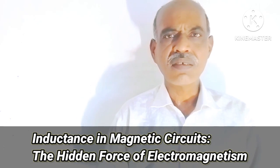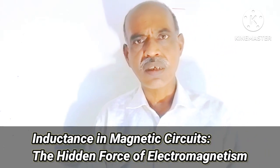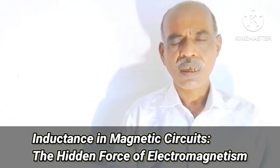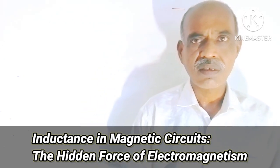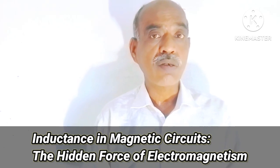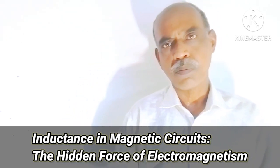Many reasons are there for which inductance may increase or decrease. Suppose air gaps are present in the circuit. If air gaps are present, reluctance increases, which means inductance decreases. That means in transformers, air gaps are not desirable unless made for specific purposes.